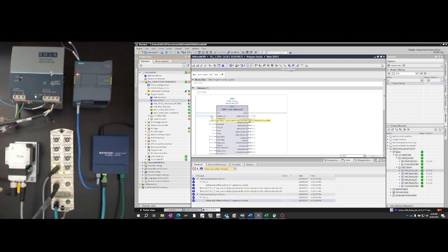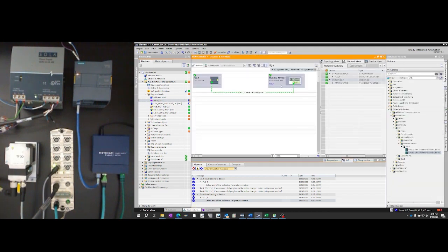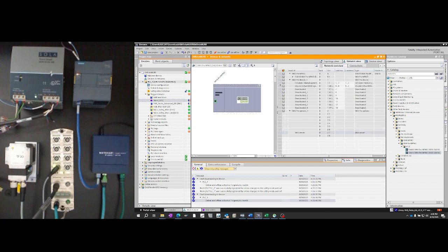It's very important for the cyclic data, the process data, that your ref inputs and ref outputs and by device available bytes be correct. So you'll need to look back at your device and network view. Under the device and network view, click the MVK Pro module. Within the device view, you can see that the IO-Link port 0 starts at input addressing 3 and output address 3.